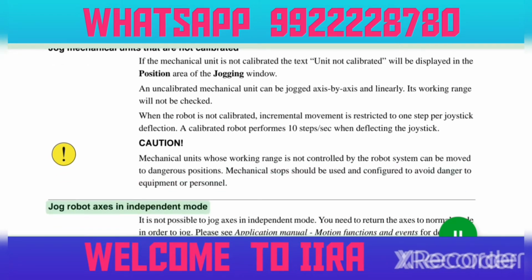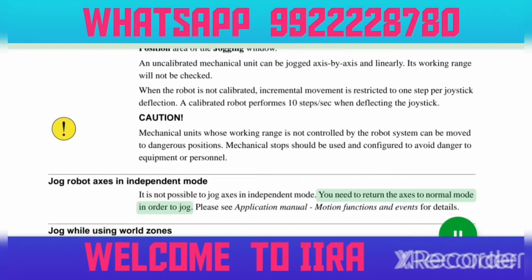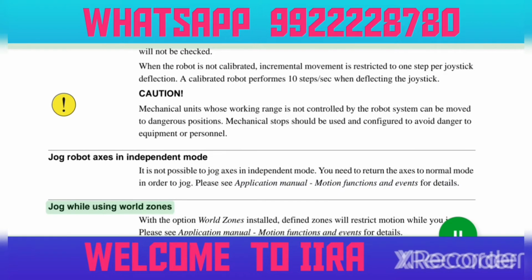Jog robot axes in independent mode. It is not possible to jog axes in independent mode. You need to return the axes to normal mode in order to jog. Please see Application Manual Motion Functions and Events for details. Jog while using World Zones.